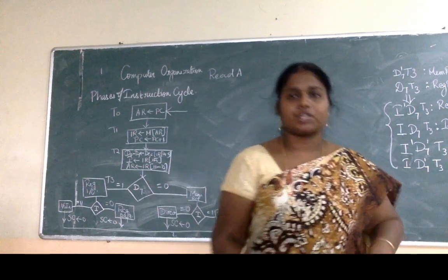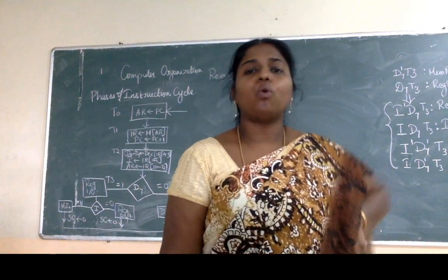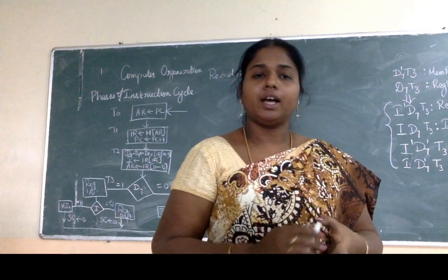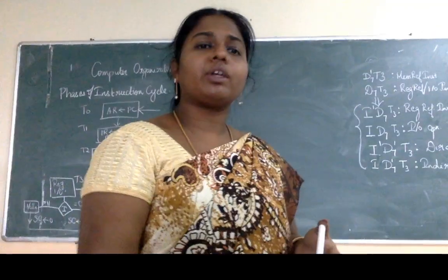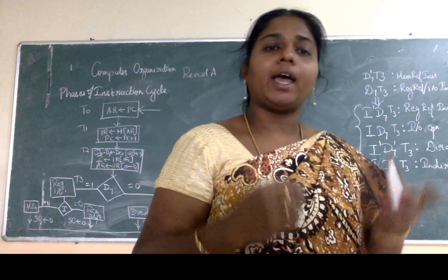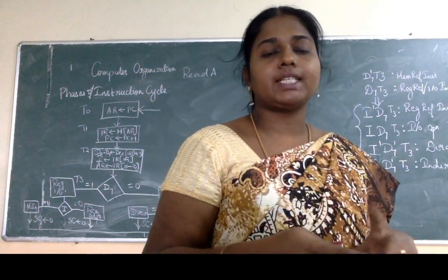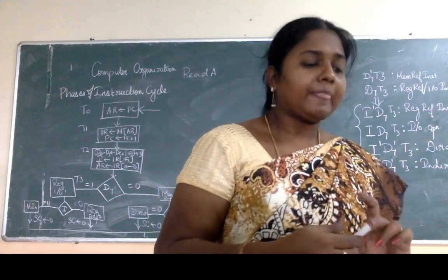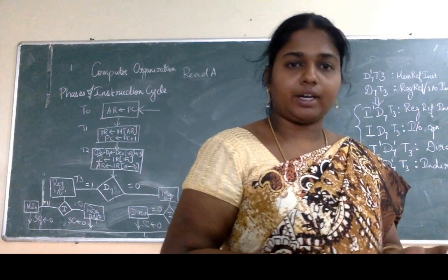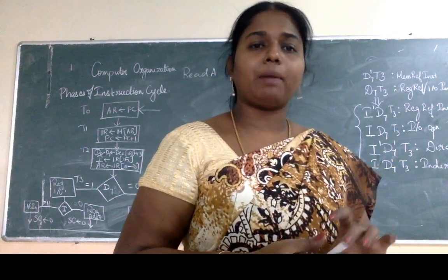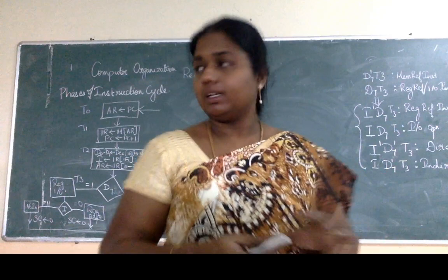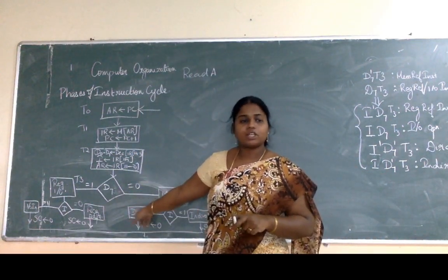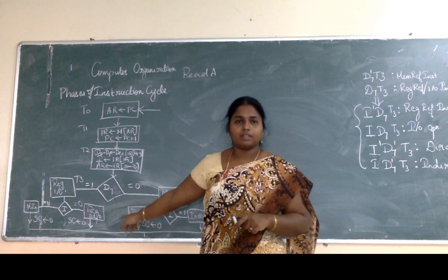Now in this session, we are going to look into what are the different instructions available under the register reference category. We are going to list our instructions one by one and see how each instruction is executed at time cycle T4 or at time cycle T3. Some of them may require time cycle T4, but most of them are executed at time cycle T3 only, because we have only done some checking at time cycle T3, so the execution will start at time cycle T3 itself.